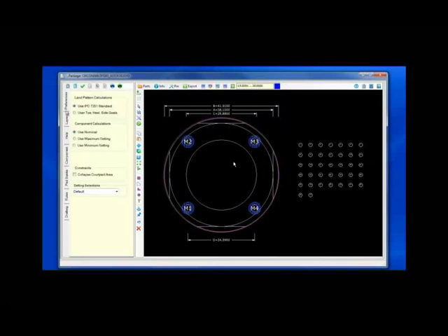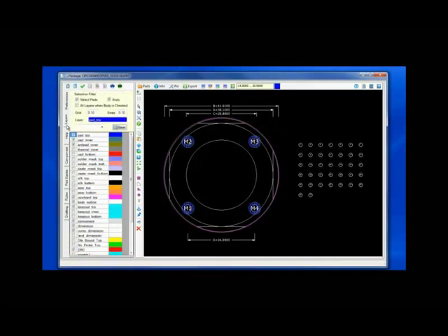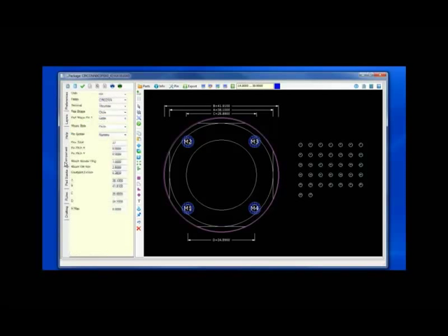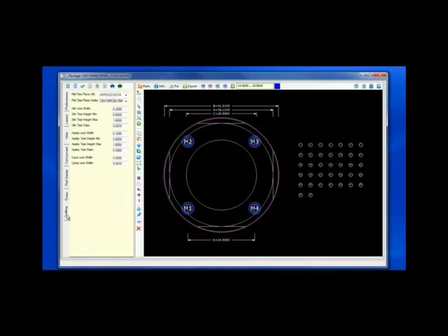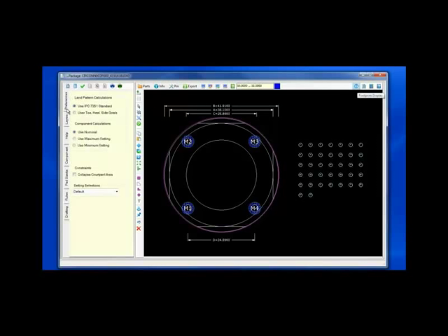Bringing up the circular connector, you'll notice the pins are off to the side. The Preferences tab contains the specific information, the Layers tab the layer information, and the Component tab contains all of the dimensioning information, plus the pad stack tabs to select different pad stacks and drafting tabs for user-specific line widths, silk screens, assemblies, and other constraints.